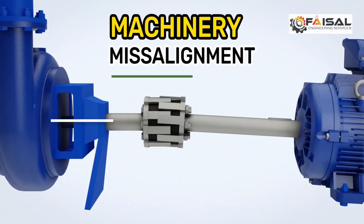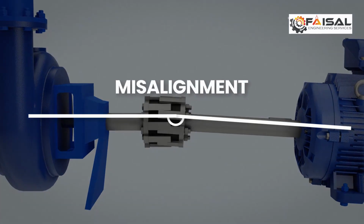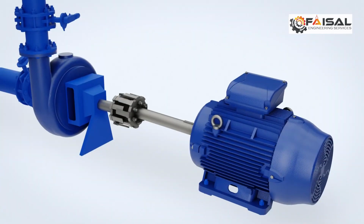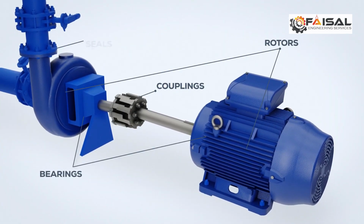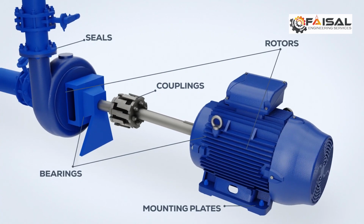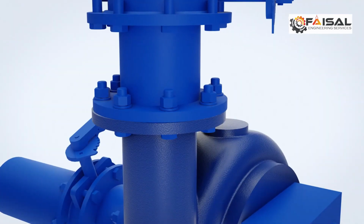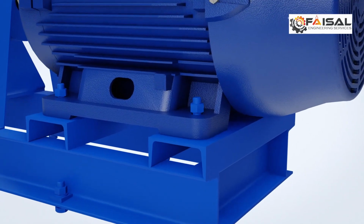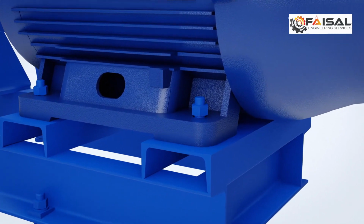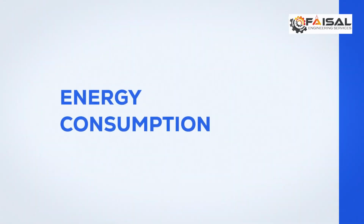Machinery misalignment is extremely common in rotating assets and is typically the root cause of machine failure. It causes excessive wear that leads to premature failure in components such as couplings, rotors, bearings, seals, and mounting plates. For example, an industrial seal failure can cause an oil leak and the machine stoppage. An excessive vibration in the fixing screws can also occur, causing a structural problem in the equipment.